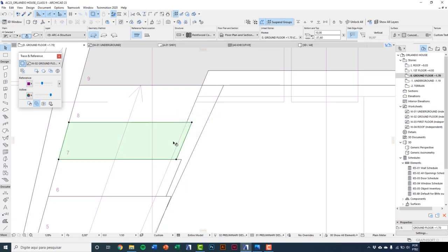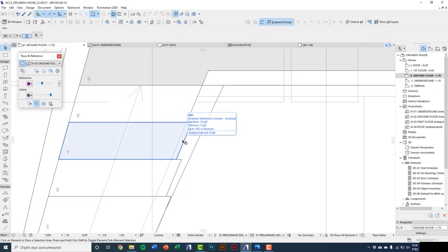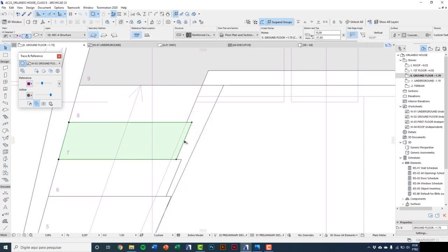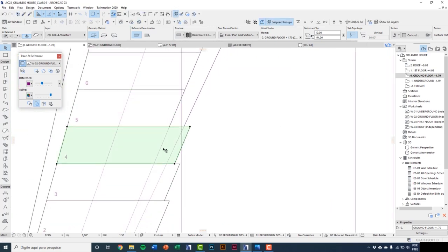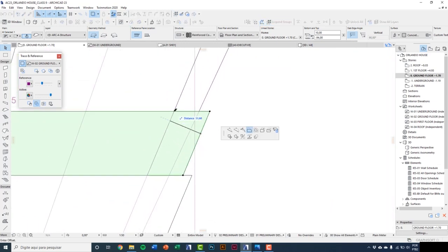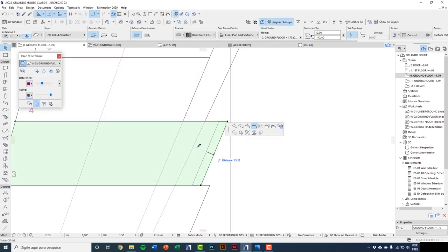So I press ESC to retire selection and clicking here at the edge, in the floating palette, I'll choose Offset Add and do the same. I'll do the same thing for all treads. You can use as a reference this black pencil or perpendicular sign.